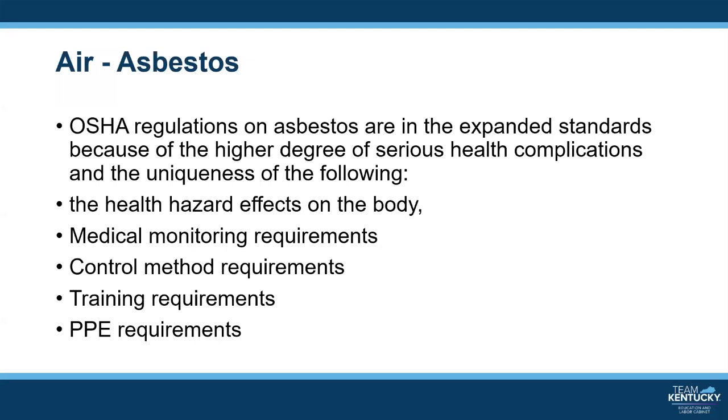Management may have extra responsibilities when the exposure level exceeds the PEL or what is called an excursion limit. This will require initial air monitoring for an 8-hour full day work shift. This could also include requirements for exhaust ventilation. It may require wet method for the disturbance of the material.